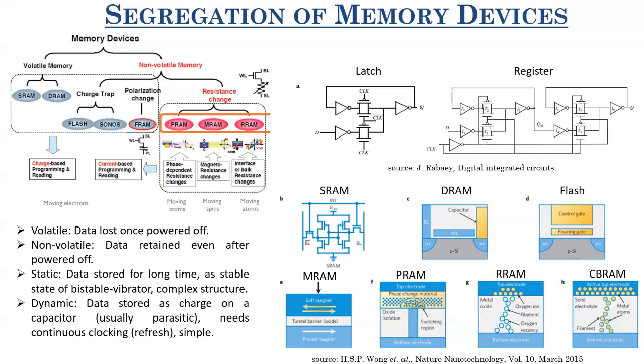So if the threshold voltage increases, for the same gate voltage which you are applying, your current is actually proportional to VGS minus VTH. So effectively your VGS minus VTH is now decreasing, and hence the current decreases. So just by measuring the current at a particular gate voltage, you can find out whether charges are present on this floating gate or not. Or, in other words, you can tune the current, or you can tune the threshold voltage of the device just by applying some voltage pulses on this control gate or the main gate of your flash devices.